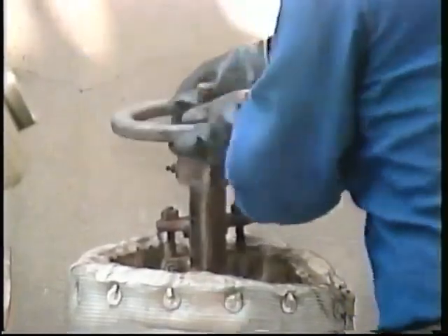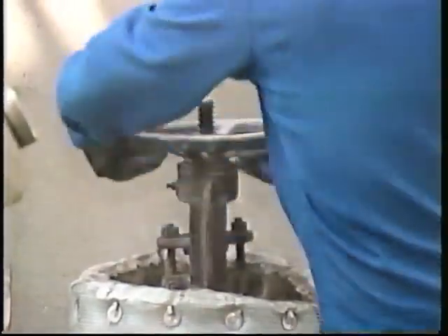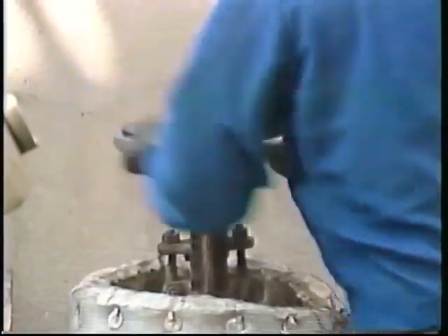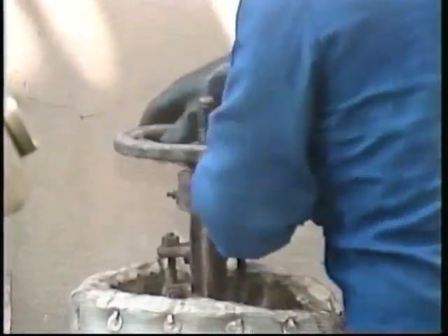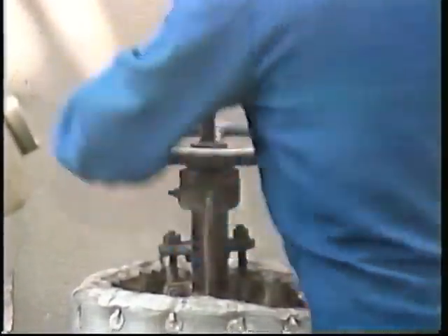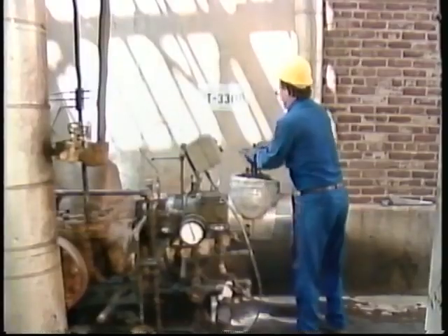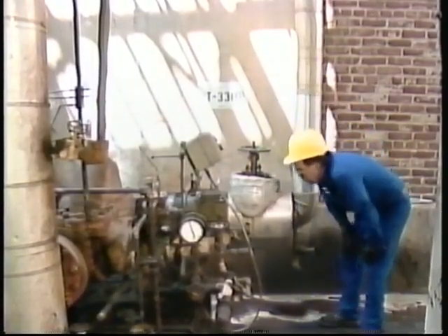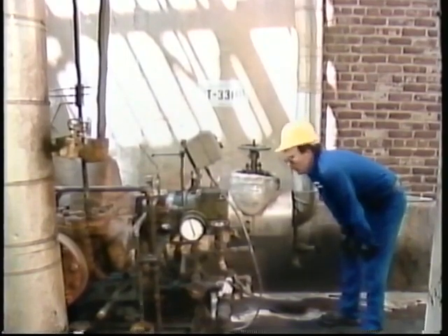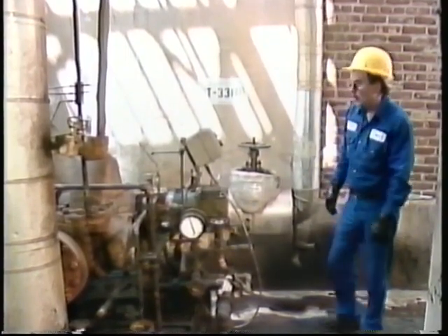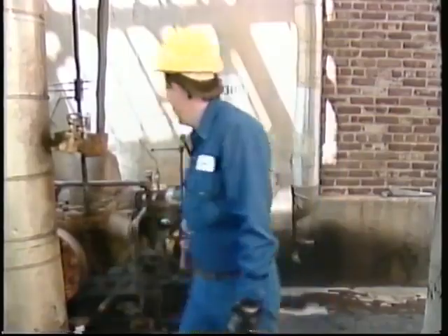Opening the throttle valve all the way before the governor has control could cause the turbine to overspeed. In turn, this would trigger the overspeed trip and stop the turbine. If the governor doesn't take over when you're attempting startup, let your supervisor know so the problem can be corrected before the turbine is allowed into operation. Once the turbine has reached normal operating speed and you've verified that the governor is working properly, the startup procedure is essentially completed.